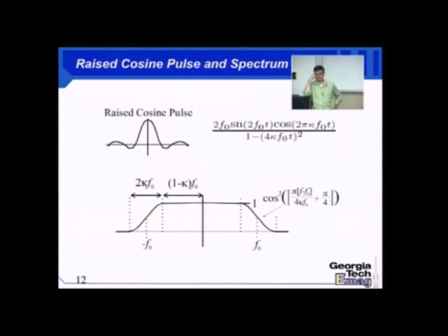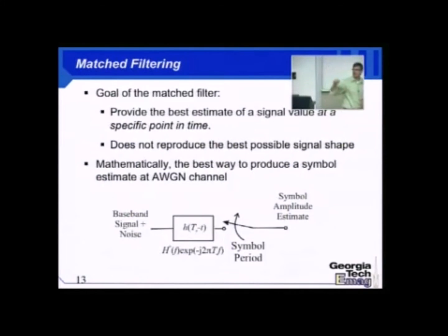This is good. It's the matched filter, right? Did you learn that in your communications classes? That turns out to be the optimal linear detector because it's not like a regular filter where you're trying to get the highest signal fidelity. You're actually not doing a really good job of reconstructing your original signal in a matched filter. But you can show that the matched filter, which is where we'll start our discussion on Tuesday, at the output produces the highest possible SNR estimate of the amplitude at that particular point. Anything before and after can go to hell for all we care, because you don't need that to detect a bit.